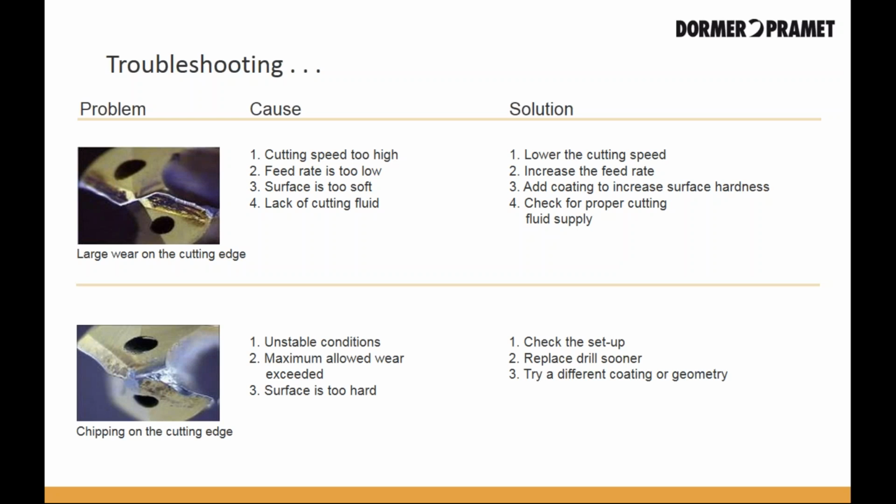Chipping on the cutting edges. The most common cause for chipping is bad fixturing or extremely hard workpiece materials. Some of the causes: unstable conditions, maximum allowed wear is exceeded, in other words, you've let the drill go too long, surface is too hard.